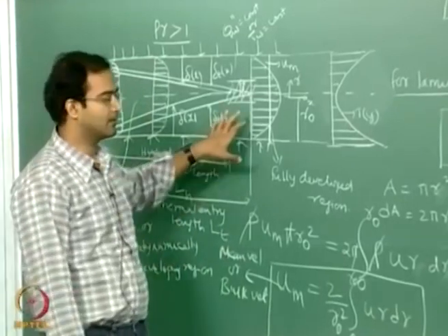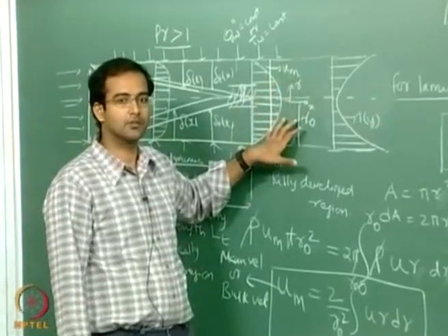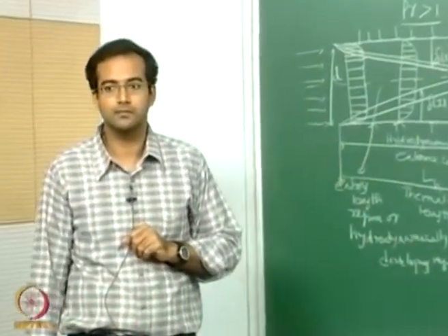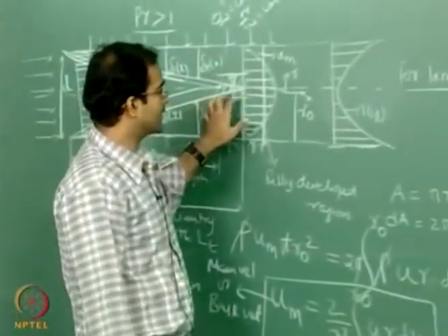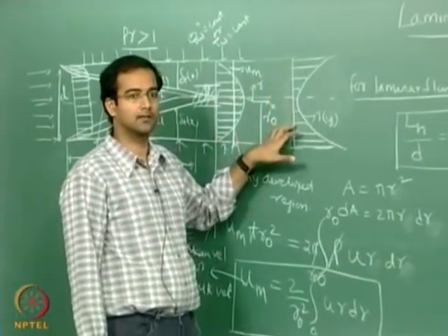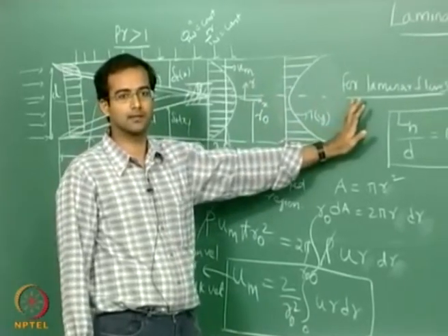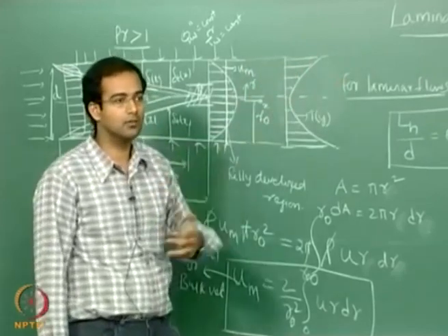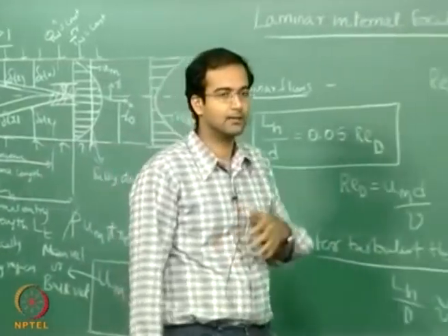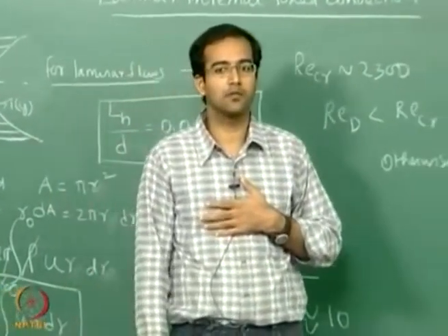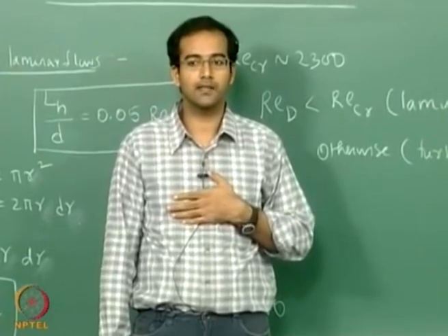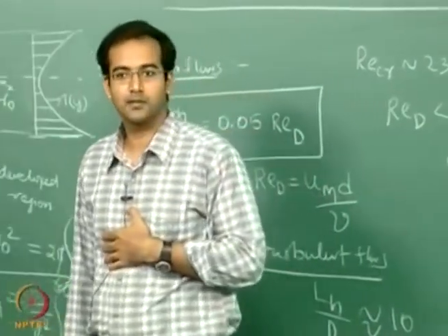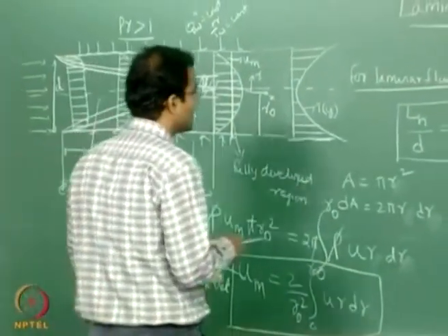So therefore, unlike the velocity profile, which shows a constant behavior, the temperature will never be a constant value, correct? So you will find the temperature of the fluid anywhere that you plot will keep on changing with respect to x at any y location, or even at the wall that also keeps changing. So how do we now look at a region and tell that that region corresponds to thermally fully developed? The criteria is we have to now develop a definition to call a thermally fully developed region. So how do we now use that criteria?